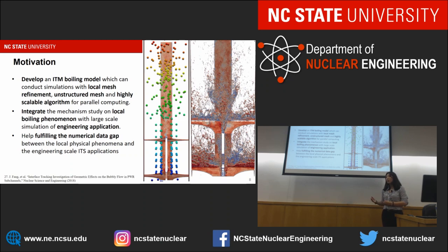But this type of model requires a lot of model closure, like bubble release frequency, bubble departure diameters. This type of parameters is hard to obtain by the traditional experiment approach because it's very hard to conduct experiments in the real subchannel scales and under the PWR and BWR conditions. And this type of simulation could help us to extract information like that.